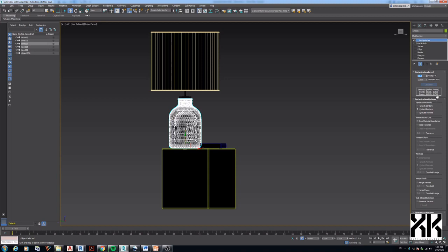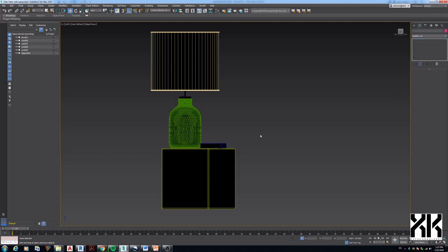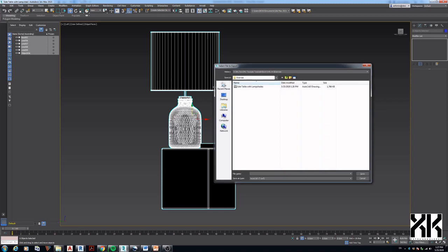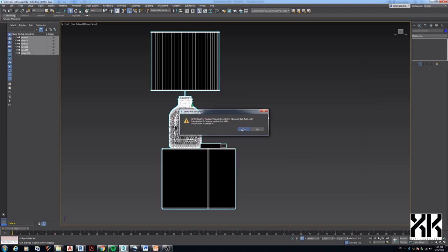We got 31,716, which means it is closer and lesser than 32,767 and can be exported. To have a better object definition, make the percentage closer, or the faces count closer to 32,767. If not for drafting, make it lower, but be sure not to deform the object.